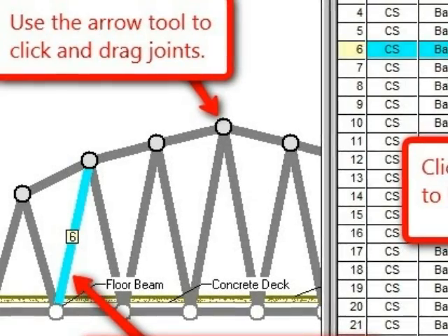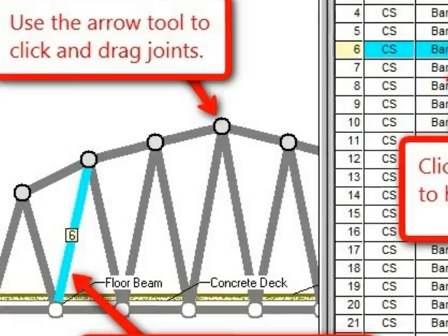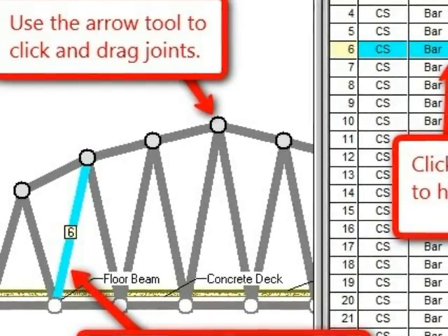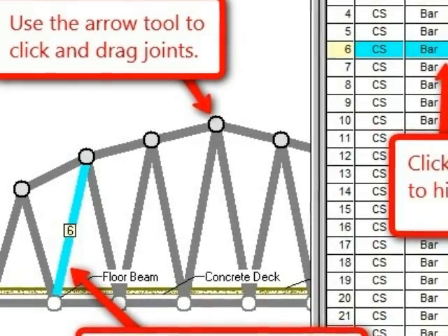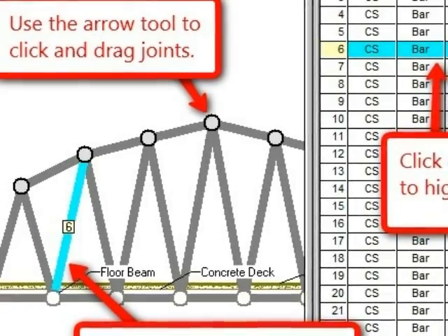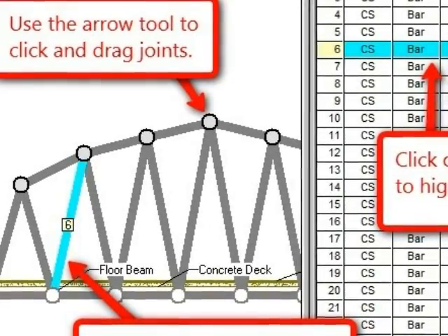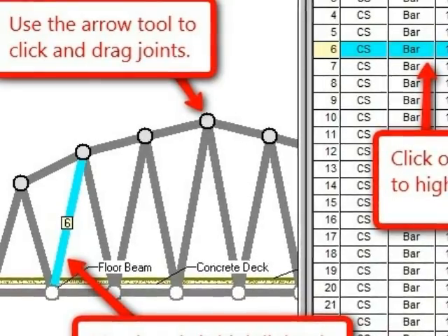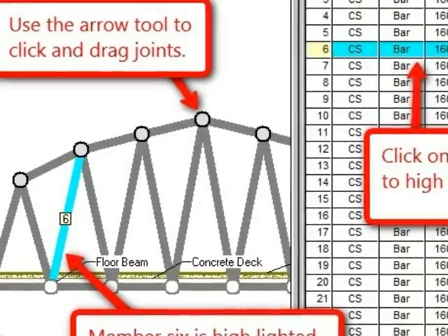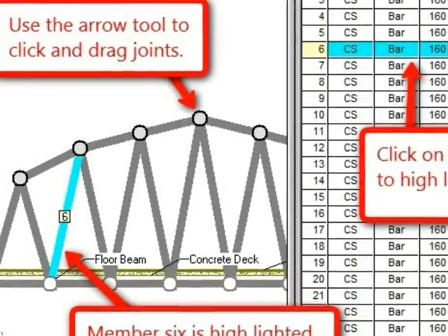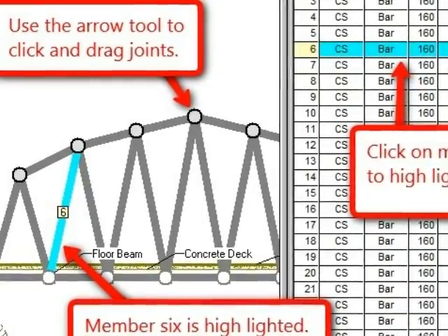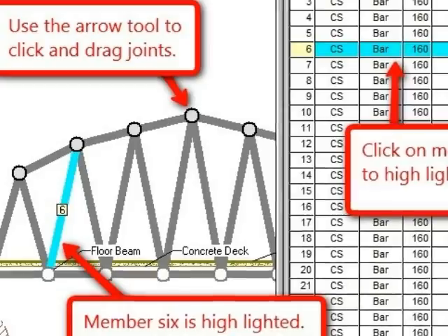In the drawing board mode, you can click on a joint and drag it to move it. See how this impacts both the cost of your design and the stress on the members themselves. You can check out the stresses by pulling out the chart on the right side of the drawing board. If you click on a member, it will highlight it on both the drawing and in the chart. The chart will tell you the relative strength of the member in both compression and tension. These numbers will be between 0 and 0.99. If the number goes above 0.99, that means that the member has failed and it will be highlighted in red.